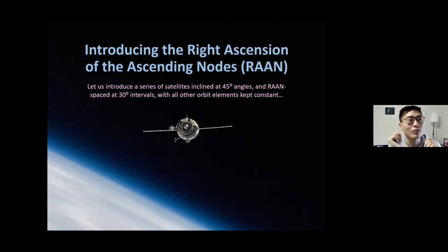And so the velocity difference in calculating a change in trajectory not only depends on your energy, it also depends on your position in space as well. There's an interesting effect about this called the Oberth effect, where you exploit differences in height. We call this the perigee and the apogee. You exploit differences in height to give you the best cost savings in terms of change in energy or change in delta V to change your orbit.